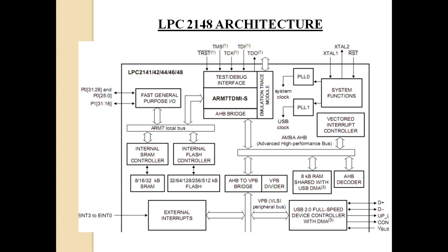Right? So if you are seeing the old 8085 kit, there will be an IC where the company name will be pasted, say VI Microsystems. One sticker will be there. So that sticker will be pasted on the EPROM. Why is that pasted? In order to cover the transparent surface. Otherwise, if some sunlight is allowed to fall on that, sunlight also will have a certain amount of UV rays in that. So those UV rays may corrupt the data present inside the EPROM. So in order to avoid that corruption, one sticker will be pasted. So that IC is nothing but your EPROM.